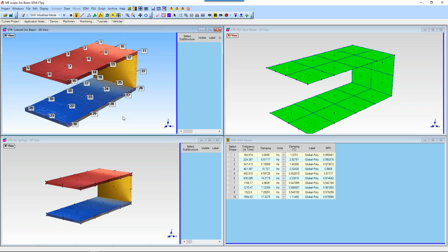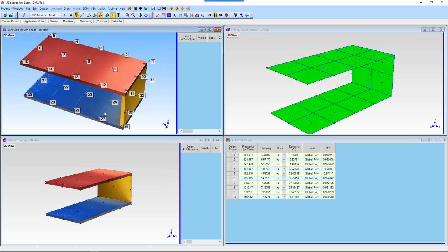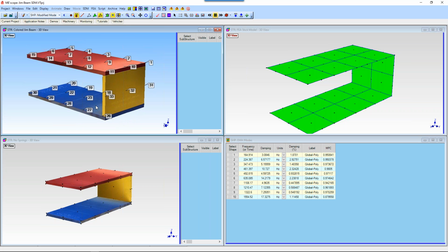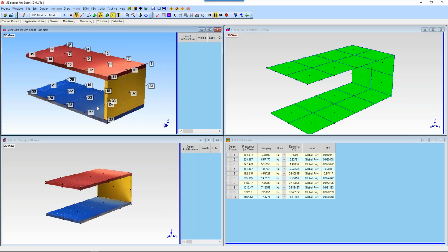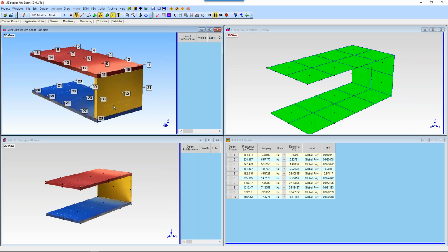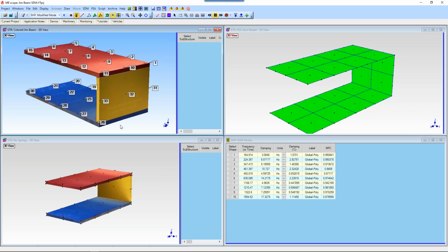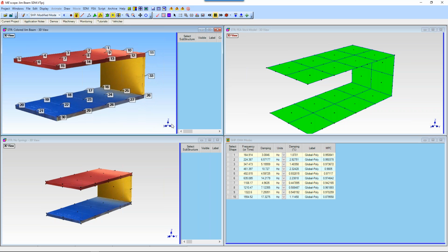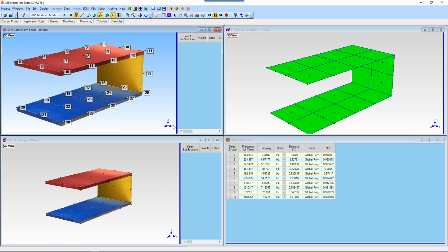And then we use curve fitting to extract the modal parameters of each of the modes from a set of measurements. So in order to take the data here, we roved a triaxial accelerometer to all of the 33 points on the model. You can see that there's 15 on the top plate, 15 on the bottom plate, and then on this vertical plate here, the back plate, there were 3 more measurements taken. So the model was set up, the orientation of the accelerometer at each point had to be included in the model so that when we do animation, we get motion in the correct directions.